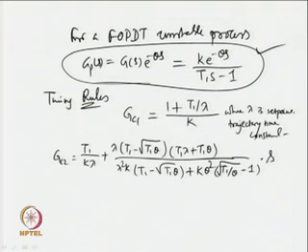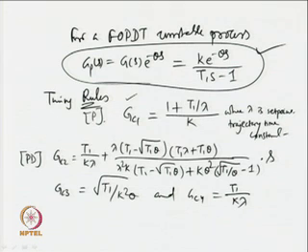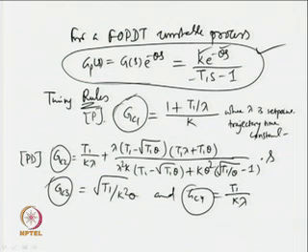So, they have used a proportional controller for GC1, GC2 is a PD controller, a proportional derivative controller, GC3 is a proportional controller having an expression k square upon theta root, and finally, GC4 is given by T1 upon k lambda. So, you know k, theta and T1, substitute over here and get the parameters estimated using formulae given over here. Okay? Using some rule they have found this, and we will see the type of performances we will get from Liu et al.'s compensator.